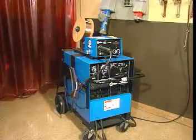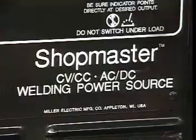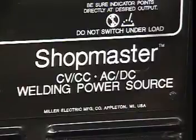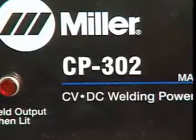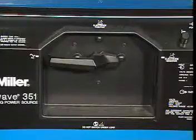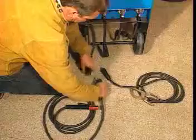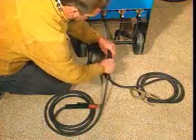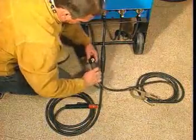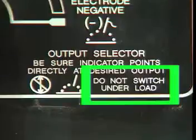Arc welding can be performed using either direct current or alternating current. These days, most welding machines are capable of producing either AC or DC welding current, although there are welding machines that produce only DC welding current. The polarity of a DC welding circuit can be changed by turning a polarity switch if one is available, or by physically disconnecting the welding leads and reconnecting them to the opposite terminals. However, a welding machine's polarity should not be changed while the welding machine is operating.